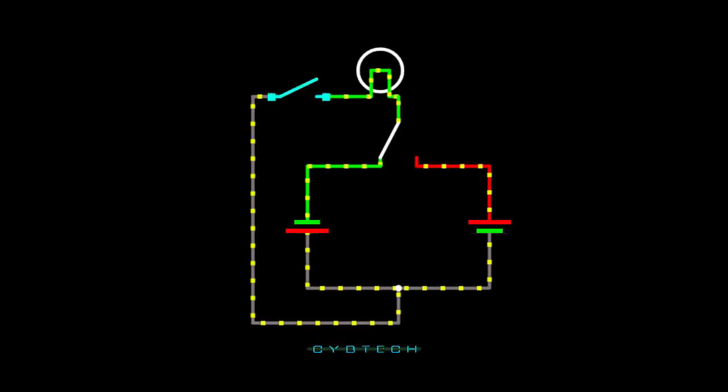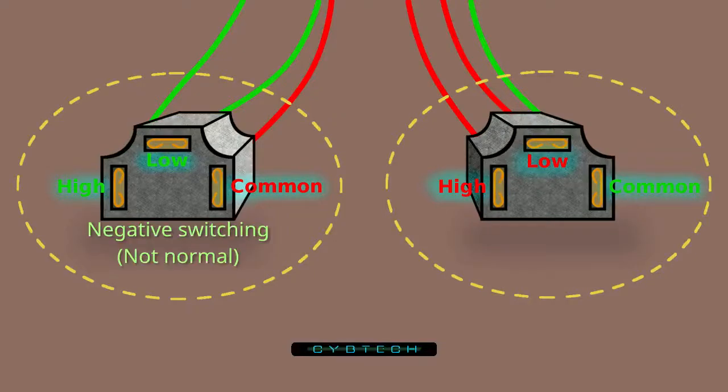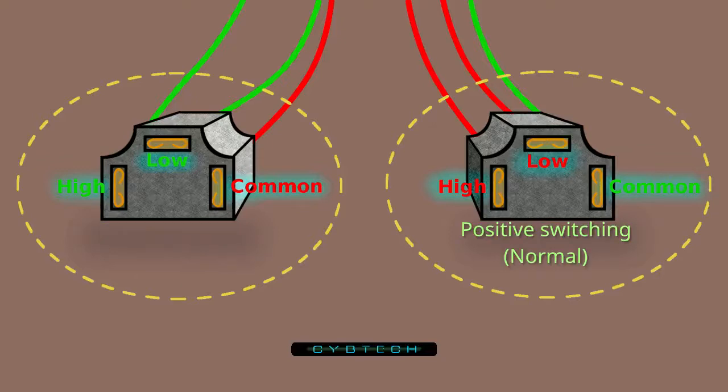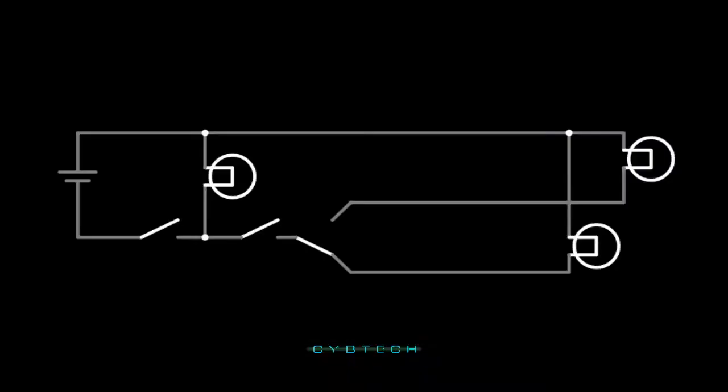about which polarity the electricity was. All they cared about was whether there was current flowing or not. They are completely passive, non-polarised devices, not solid-state devices. So I deduced that the headlight circuit was switching the negative or return to earth or chassis, rather than switching the positive. So the circuit looks something like this.